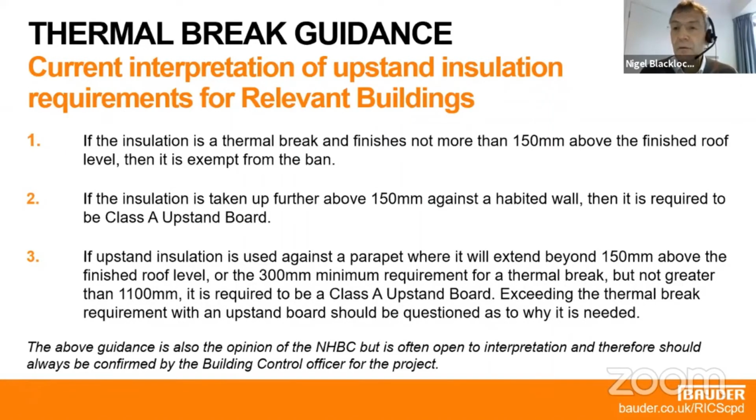I've just added a little note at the bottom there. Working with the NHBC, we came up with this general guidance. They acknowledge that a parapet wall, the inside face, is covered by Approved Document B, but they take the pragmatic view that up to 1.1 meters high, they don't see that as a problem. I think if you went above that, you would certainly need to seek advice.